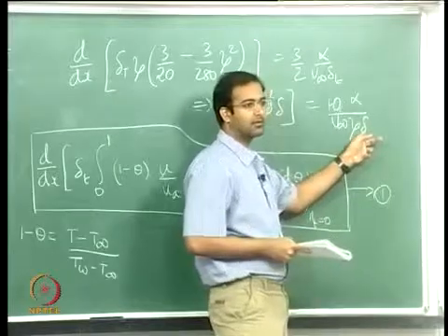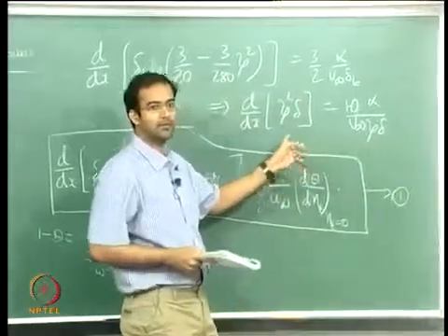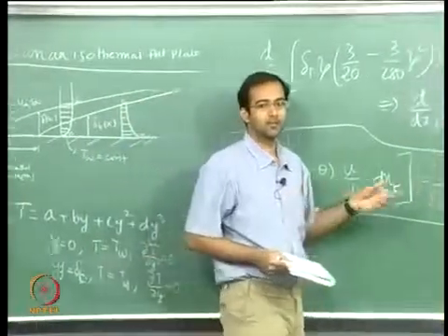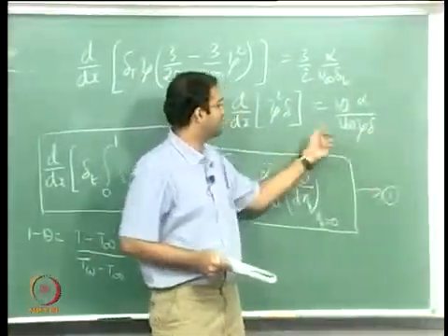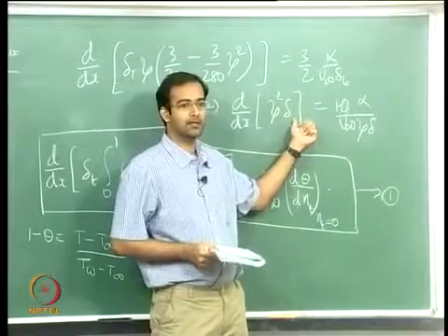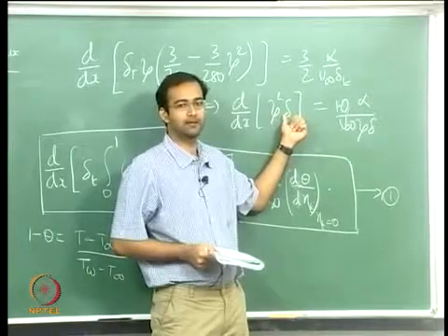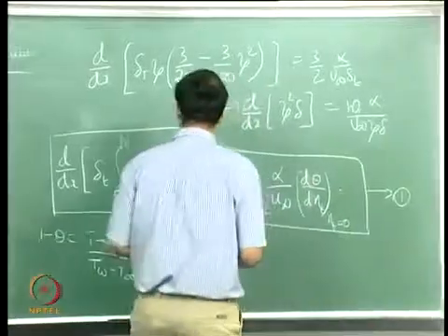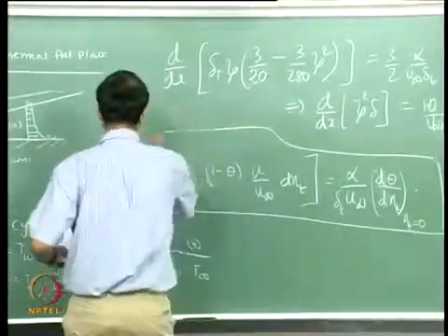So finally I am reducing the entire equation to an equation only in terms of delta and zeta. I know now the expression for delta coming from the solution to the momentum integral equation, which I can substitute into this, and now I will have an ordinary differential equation in terms of the unknown zeta. With that I will be able to calculate also my thermal boundary layer thickness.